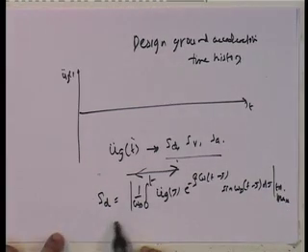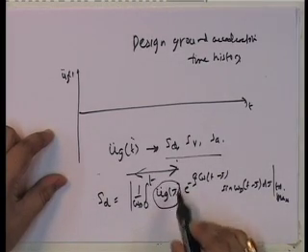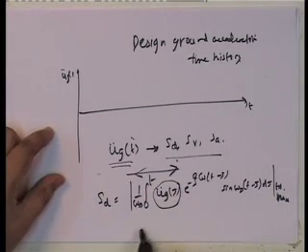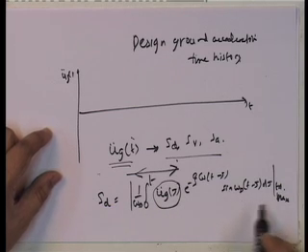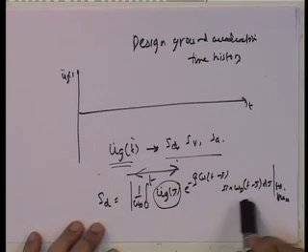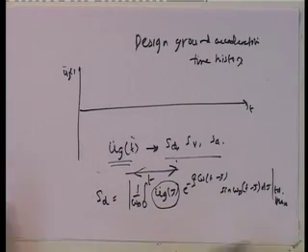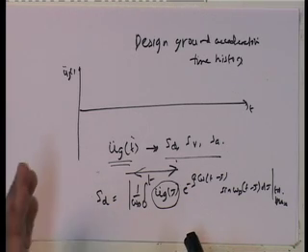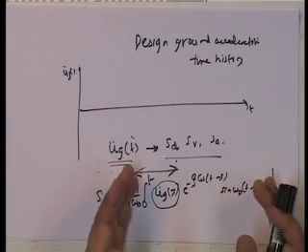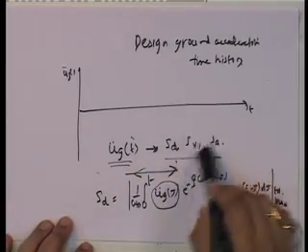So, SD is, if you have this time history, this is a known time history. By solving this, we've already talked about various ways of solving a problem. The Duhamel integral can be solved numerically, or you can do time marching schemes. Once you get your deformation time history, you take the peak value, and that is SD. Once you know SD, you know SV and SA.